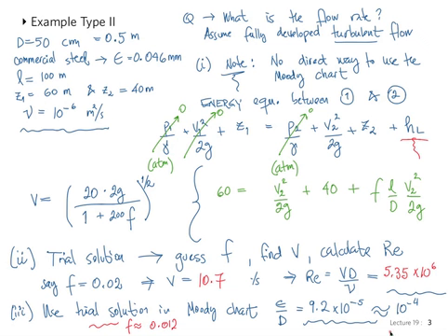The friction factor that we chose, we chose one completely at random. It was just a wild guess. And we calculated everything and we obtained something smaller. So we need to recalculate velocity and everything, go back in the Moody chart and see what comes out. I actually got the same value, about 0.012. It doesn't change, and if you're not getting any change, then that's when you stop.